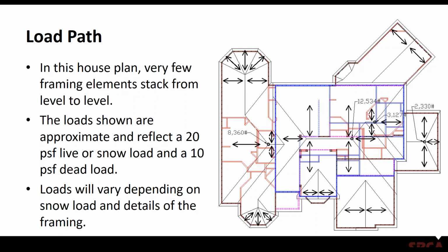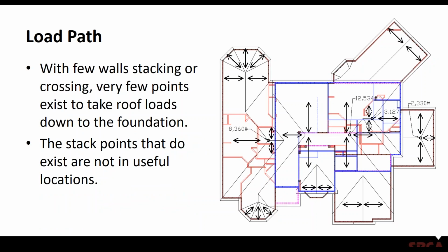And there's a good chance that, if there's a beam on the floor or floors as you work your way down, they need to be able to pick up those loads and transfer those loads to the load bearing walls and ultimately get them down into the foundation.